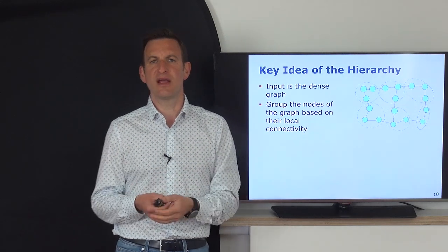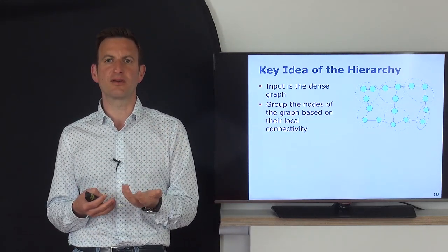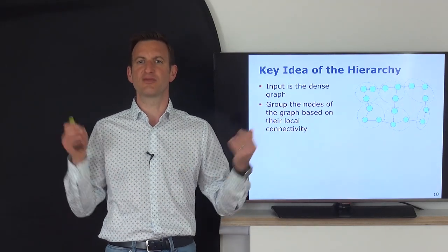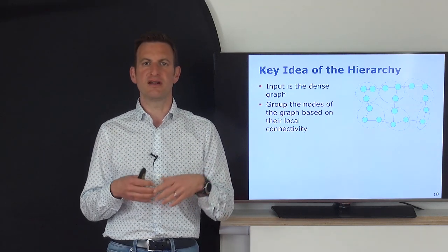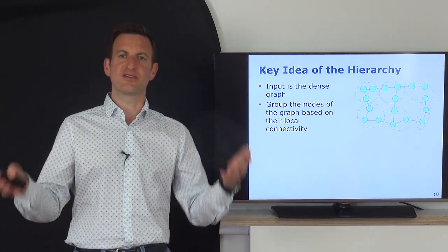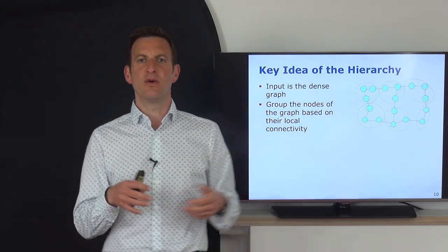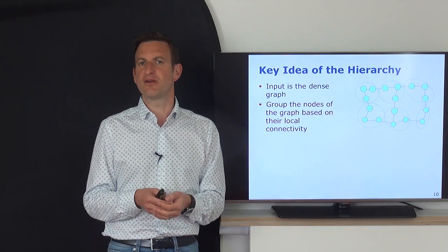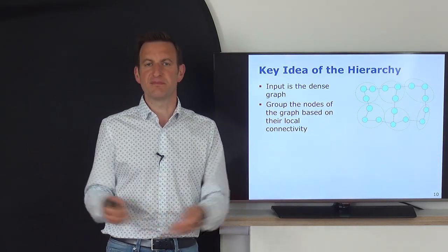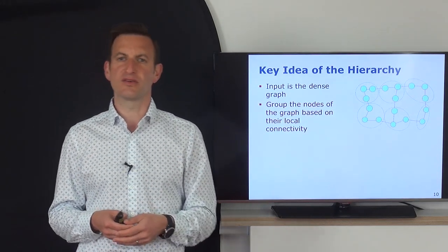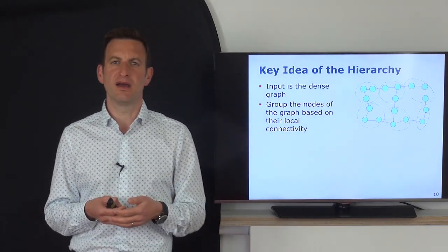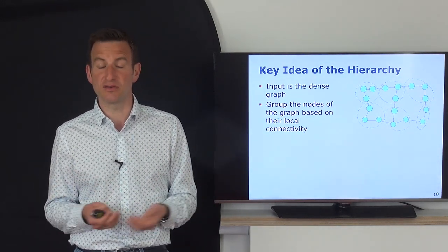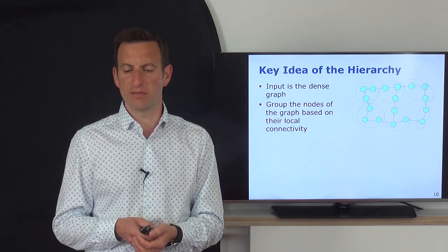And there are different ways how we can form those groups. This can be a very simple criterion, such as whenever the robot traveled more than 50 meters, we just create a new local submap. We may have smarter ideas if we can determine, for example, intersections in an environment. We may break it down within intersections or any other technique we want to use. But in my experience, often a very simple threshold, like we have moved more than 20 meters or something like this, is a very good starting point. It's very easy to implement, easy to debug, has a very small number of side effects and performs pretty good. So there's typically no reason to do something substantially more complicated.